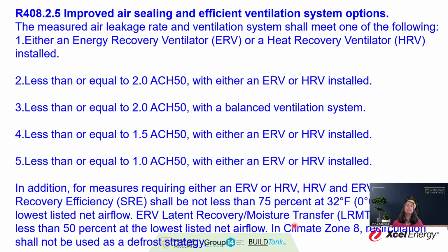Improved air sealing and efficient ventilation options. So this is saying, okay, you have to meet one of the following. You either have to have an ERV or an HRV that's installed. Then you also have to demonstrate that you have air leakage rates that do not exceed what you see on the screen here.